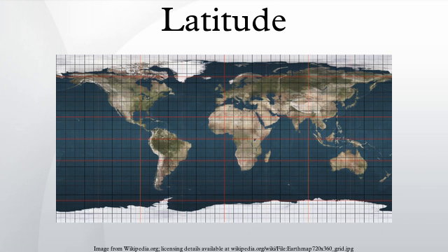Length of a degree of latitude. In meridian arc and standard texts it is shown that the distance along a meridian from latitude φ to the equator is given by the following. The function in the first integral is the meridional radius of curvature. The distance from the equator to the pole is the following. For WGS 84 this distance is 10,001.965729 km.